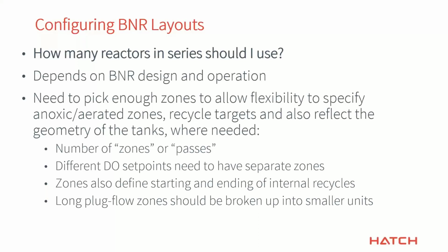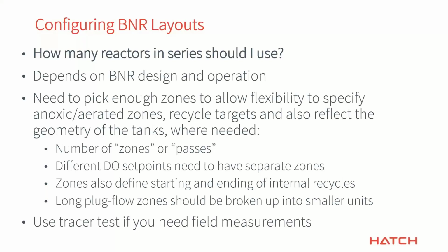So I've been to a couple places where, when we got to the aerobic zone at the end, it was actually quite long and skinny, 4 times longer than it was wide. So that is a little bit plug flow. So we kind of broke that up into 2 zones or 3 zones sometimes. So it's kind of a bit of an art, but those are things that are required for you to be able to set it up the way that you want to.